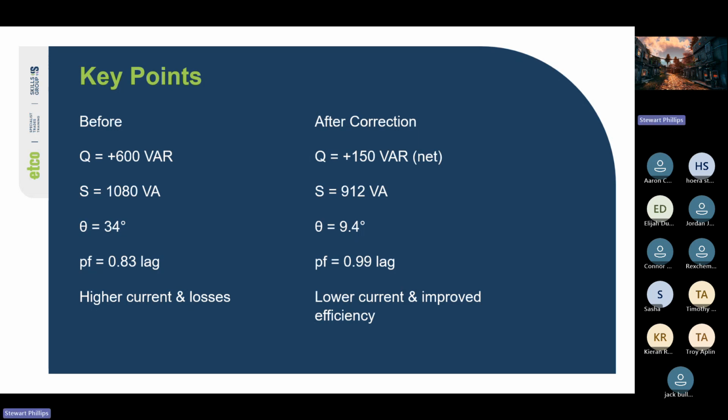The opposite is also true. If our power factor is too capacitive, then we need to add inductors into the mix to change things up. Back in the early days, when they first started turning on a lot of the LED lights in these big apartment buildings in Wellington, they all of a sudden had a power factor going the other way, and they weren't sure how to fix it.